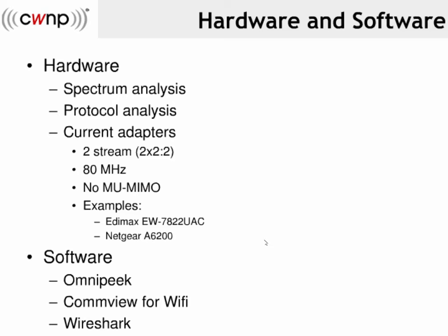Now, if you want the software to use some intelligence and figure some things out, looking at what we might call fingerprinting or some other term for identification, what the actual channels are, and that they are 802.11ac 80 megahertz channels, for example, then you would need to update the software. But the actual spectrum is just what it is. It's the frequency space. You can see the energy. And so you can use your existing analysis software and hardware and actually see activity. But if you want, again, features specific to AC in the software, then the software would need to be updated.